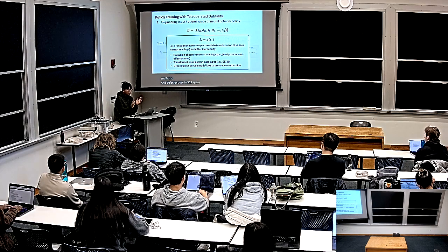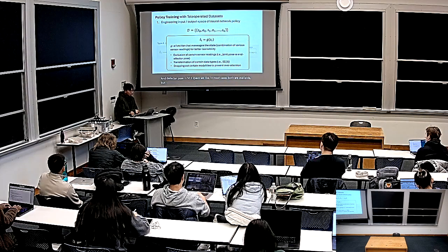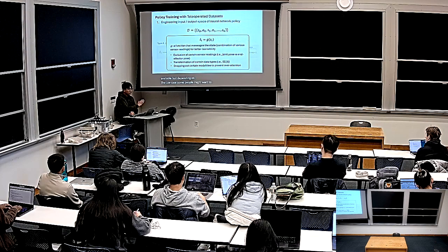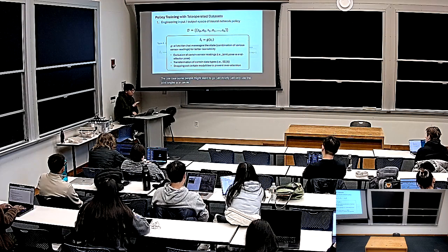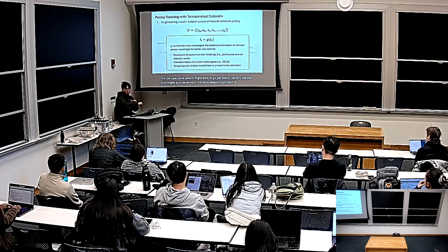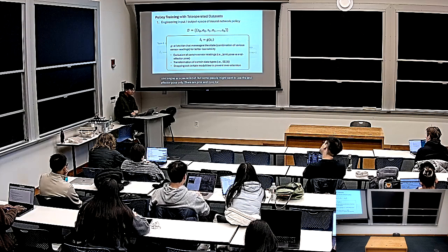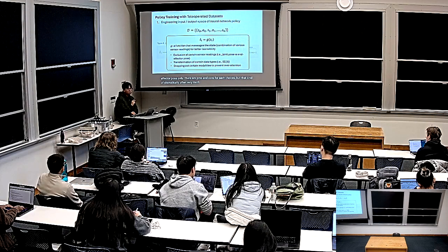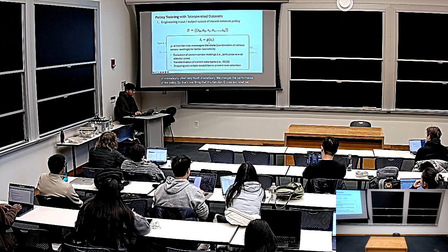In most cases both are available, but depending on the use case, some people might want to use only the joint angles as a policy input, while others might want to use only the end effector pose. There are pros and cons for each choice, but it often dramatically changes the performance of the policy. So that's one thing that this function G does, and what we robotics practitioners do.